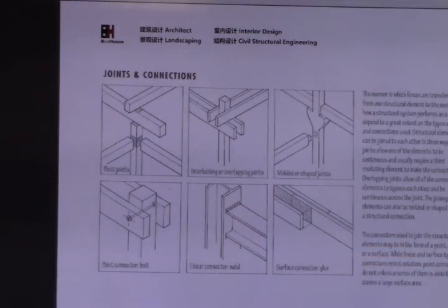The bolt connection can be a pin connection or a moment connection, depending on how many bolts you use and how you arrange the bolts. Yeah, that's a lot of things. This is just general speaking.